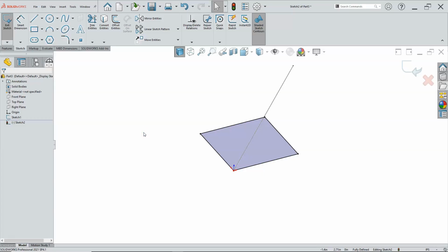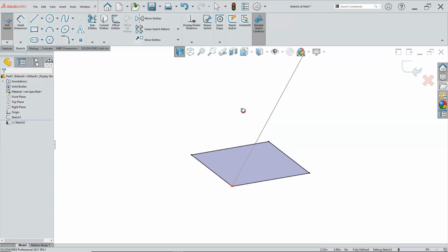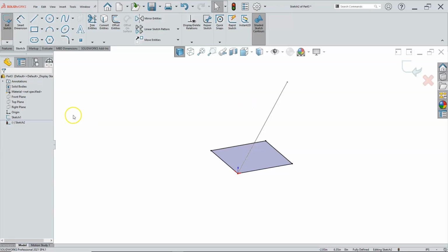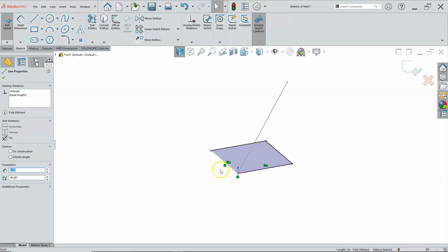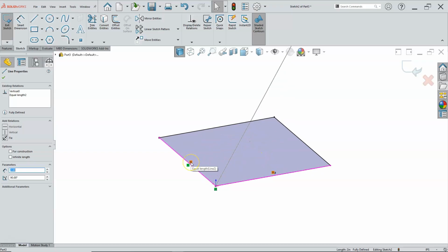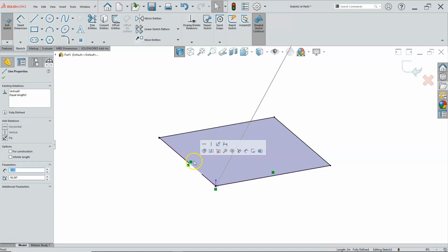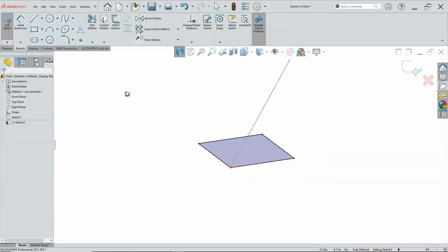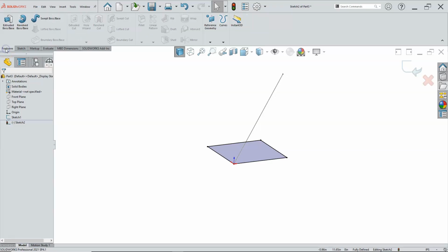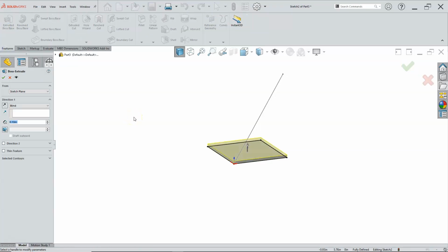And using those geometric constraints, those relations, we can generate a lot of complex geometry with very little effort that is going to be stable. And if something happened that I decided that needed to be the rectangular, I would remove the equal. I can highlight it and hit delete on the keyboard, or when it is selected in the property manager, I would delete the equal length. So once we set these, they're by no means permanent, but we do have to manage them accordingly.